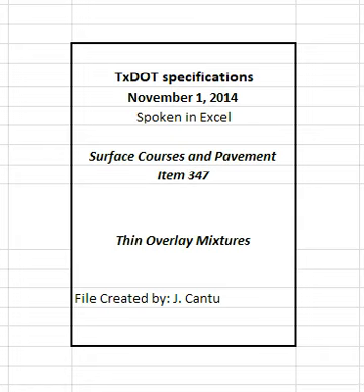4.4.2.1.17 JMF adjustments. If JMF adjustments are necessary to achieve the specified requirements, make the adjustments before beginning a new lot. The adjusted JMF must be provided to the engineer in writing before the start of a new lot, be numbered in sequence to the previous JMF, meet the master gradation limits shown in Table 6, and be within the operational tolerances of JMF2 listed in Table 8.